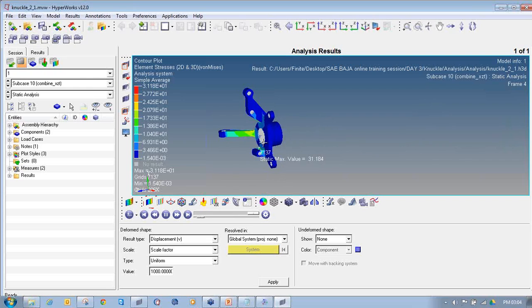So in this way, this video explained how to do the 3D meshing, how to improve the mesh quality, and how you can use the combined loading. So you can follow the same process to apply the different loading conditions as per your requirements. The process will be same. Go to MPC, create load collectors, define rigids, and then apply forces, and then perform the different loading conditions. You can use the load card to combine them and apply the different loads at the same time. So in this way I have ended this video.